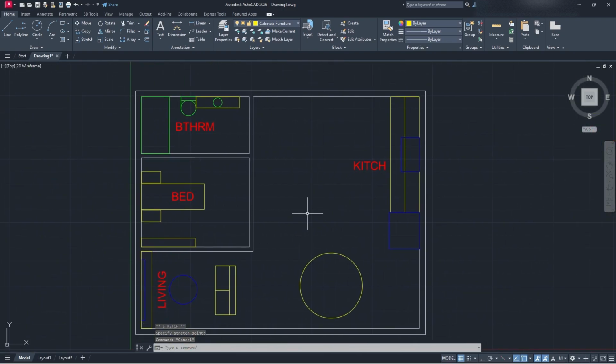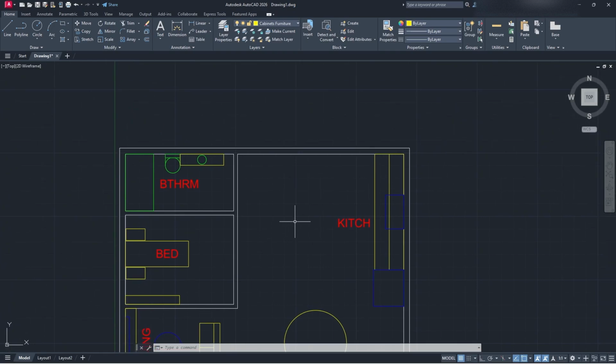So the next important thing to do is to make your windows and to make your doors. When you're making a doorway, you want to make sure that your doorway is actually how big a door is going to be. So this also depends on what kind of door you're using. If you're going to do a double door, then it's going to be obviously double what it's supposed to be. But if you're using a single door, you're going to be using generalized measurements. In this case, if we're in an apartment, an interior door is probably anywhere from 24 to 36 inches, and then it's probably about 80 inches high. So we don't really need the height in this case.